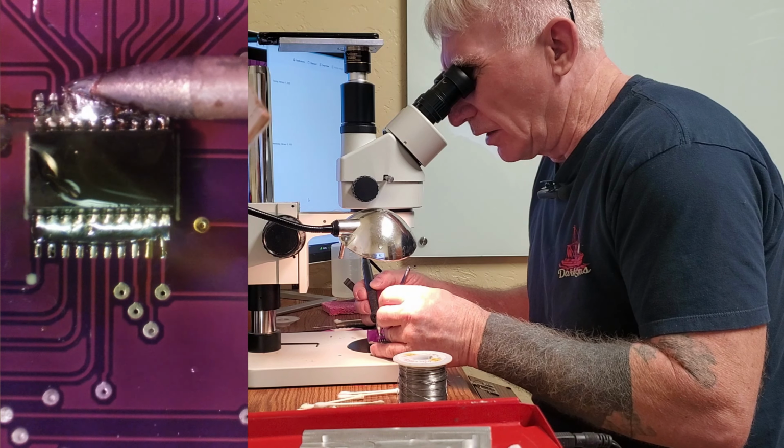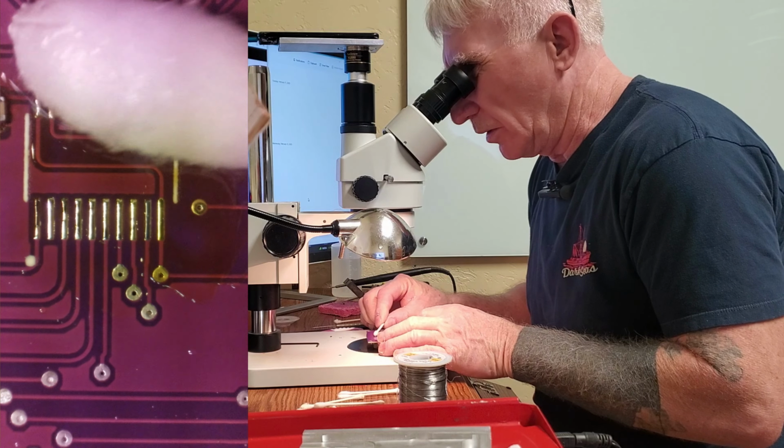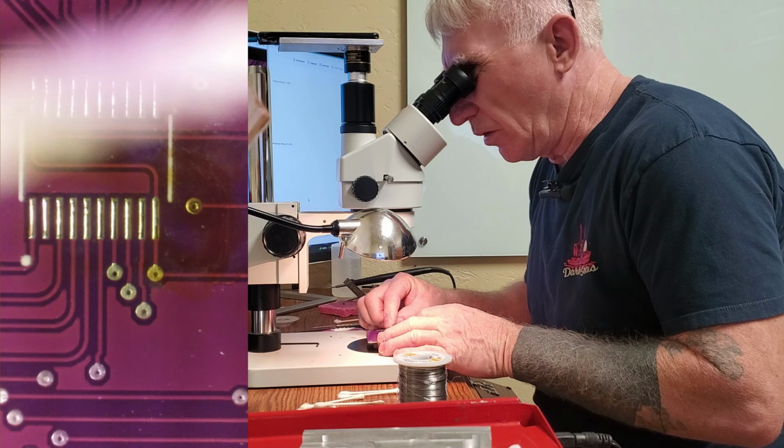Okay. Got it with our tweezers. And we just put it over here on our sponge to dry off. So we did it pretty good. It's clean. It's clean enough for right now anyway. All right. So let's clean that flux up before it gets too dried and hard. And we can reuse that chip too if it's good, but we don't know. So we'll probably just replace it. That's why I ordered 2. I should have ordered maybe more. But I think we're okay. We just got to pay attention to the outputs.